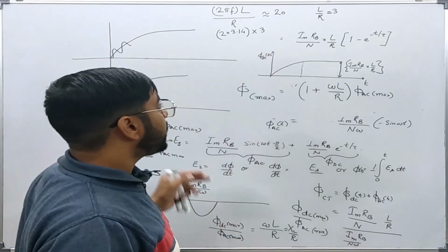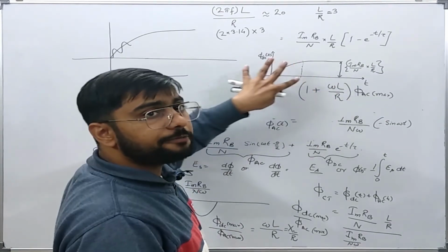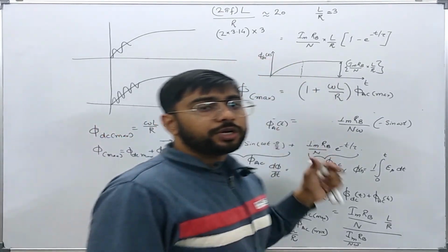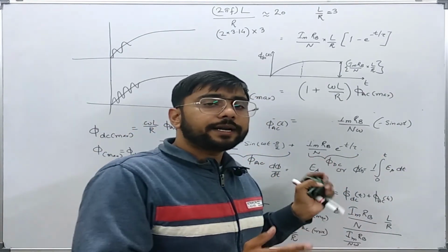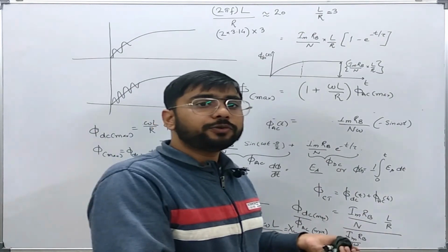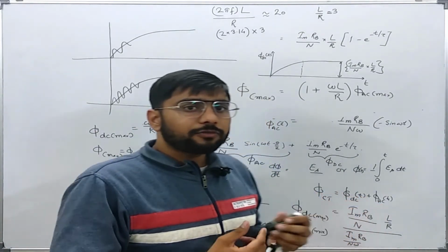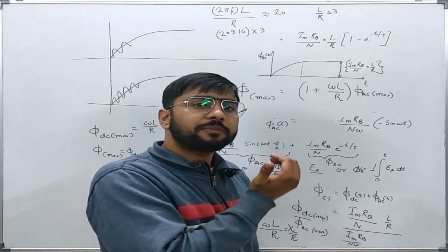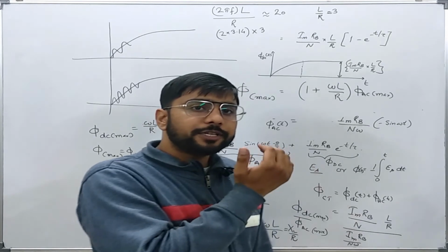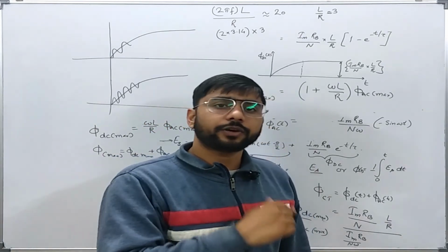To cater for this heavy flux, during construction we should either take the core material to be very high, that is have excessive dimensions of the CT, or, if we cannot do that, adopt some special design, like introducing very small air gaps which do not interfere with the excitation characteristics of the CT core.